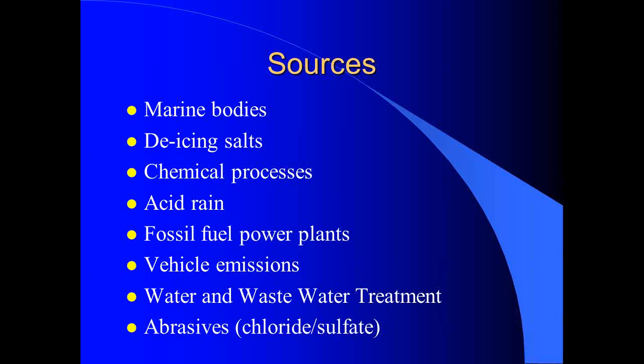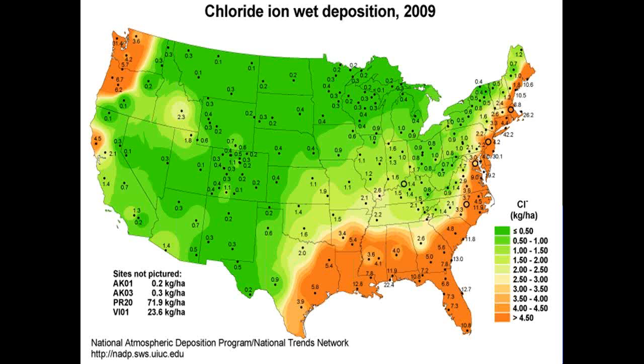It may be a very low level, it may be below the allowable level, but anytime you get contamination on a clean surface, it's very hard to get that surface back to a totally non-contaminated level to get the most lifespan as possible out of a coating. So even if you're adding only a little bit of contamination, it's still impacting the overall performance over a 20-year period.